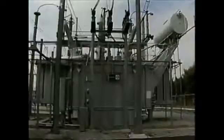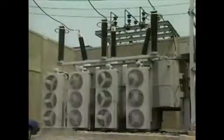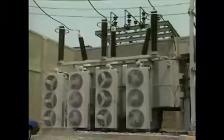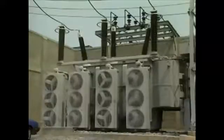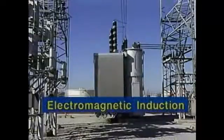Some of the main components in a plant's electrical distribution system are transformers. Transformers increase or decrease voltage from one electrical circuit to another. By doing so, they enable an electrical distribution system to provide different voltages to different types of equipment. All transformers work on the principle of electromagnetic induction. The application of this principle enables power to be transferred from one circuit to another, even though there's no physical connection between the circuits.